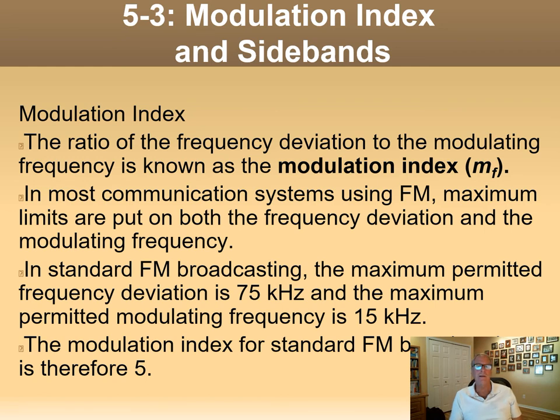Well, think about that. Our hearing, supposedly, not mine, but some of us anyway, still has 20 hertz to 20 kilohertz. Well, the FM band limits it to 15 kilohertz, so you're chopping out the top 5 kilohertz. Not uncommon for a lot of what we listen to these days. Compressed audio is a very similar scheme. They save bandwidth, they save bit rate for your streaming devices by chopping off the top 5 kilohertz. So most of us can't hear that anyway. I know I can't. Haven't been able to for a long time.